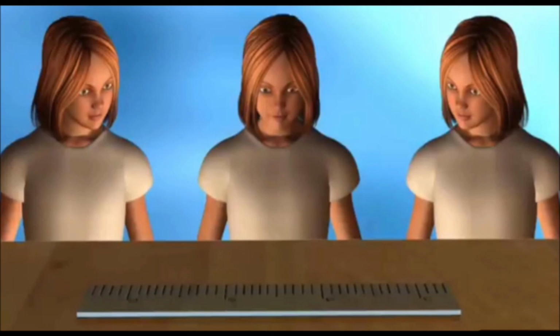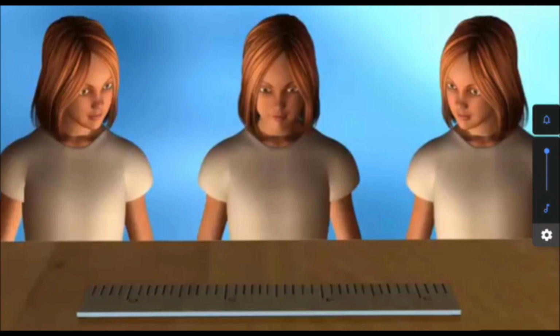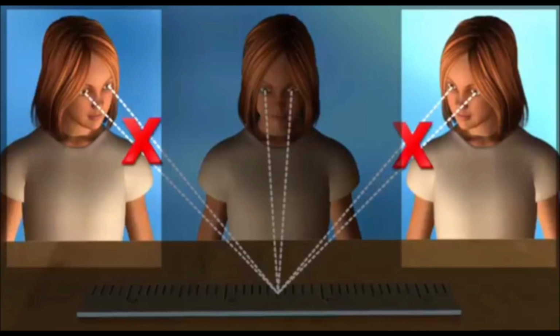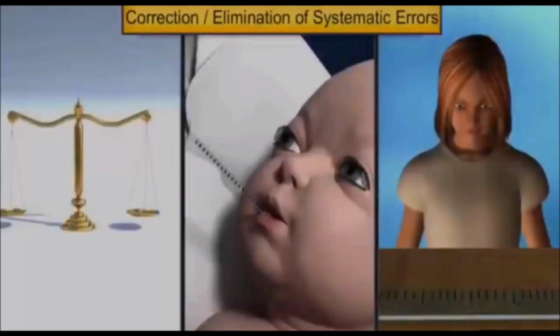Right? If I take a scale measurement, the position and tilt of the head should be proper. If I view it from the left or right side, my head is tilted, so the measured value will be very long and it will show an error of 0.1 millimeter or so. Therefore, I have to measure at a straight angle, with my eye position on the scale. Right? So left side and right side measurements are wrong. Only the position should be what?